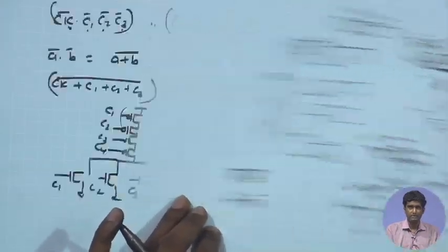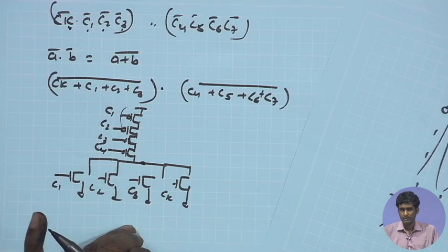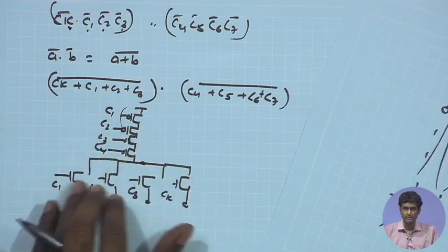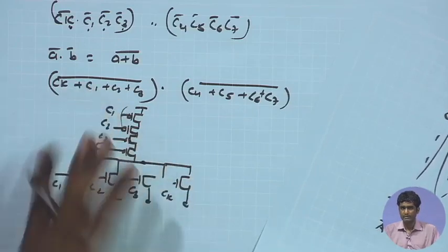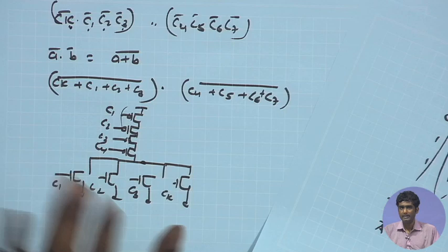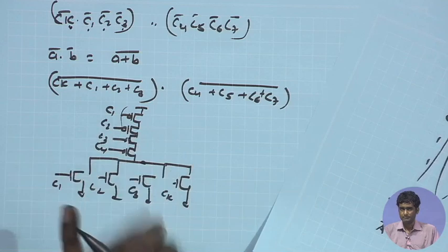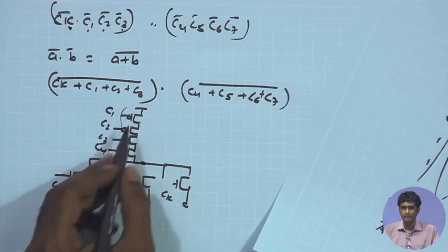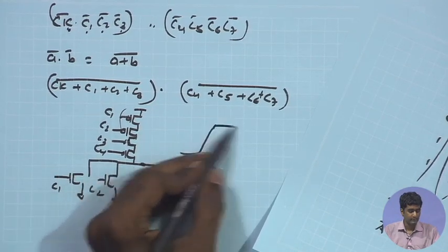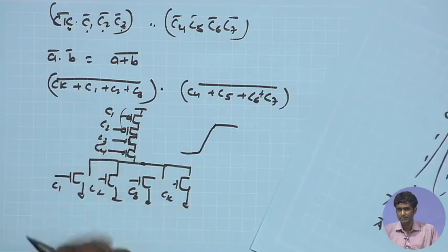So, generally for high speed logic we may prefer NAND gate implementation, but in our case that is not an important concern, because logic speed is not very high. As a result, we can go for NOR gate implementation also. So, you should be aware of the logic design. If you are supposed to implement any logic gate using transistors, you should know how to split it and implement it using smaller gates, so that the delay is within limit and you have the right kind of transitions. Along with the delay, another point is rise and fall time. If you stack more transistors, because of the large RC time constant, the rise time and fall time will also be degraded. So, these issues should be kept in mind while implementing transistor level logic.